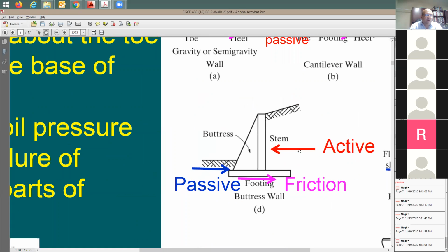So we're gonna have some active pressure coming here to push the wall, and the soil is gonna start to crack, and the pressure is gonna be smaller, kind of, like lower in value. And this passive pressure is gonna be high, is gonna be coming when you push this wall against the soil. Because the total amount of pressure that you have here is gonna be larger than this. The pressure intensity itself here is gonna be smaller, but the total pressure is big. So the wall is gonna start to move left. In this case, you're gonna see this soil here is gonna be exposed to pressure, so the intensity is gonna be high, but the amount of total pressure is gonna be lower than that for the active.